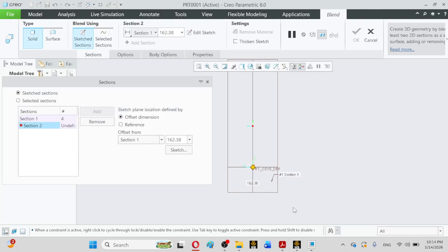Here the important thing you actually observe is that whenever you draw a complete circle without using the divide tool, it actually lists here 2 segments, because one is the circle center and the other is its boundary. But when you divide it in 4 segments, you may expect that there might be 5 total segments, but it lists here 4, because at that time it omits the center of the circle.